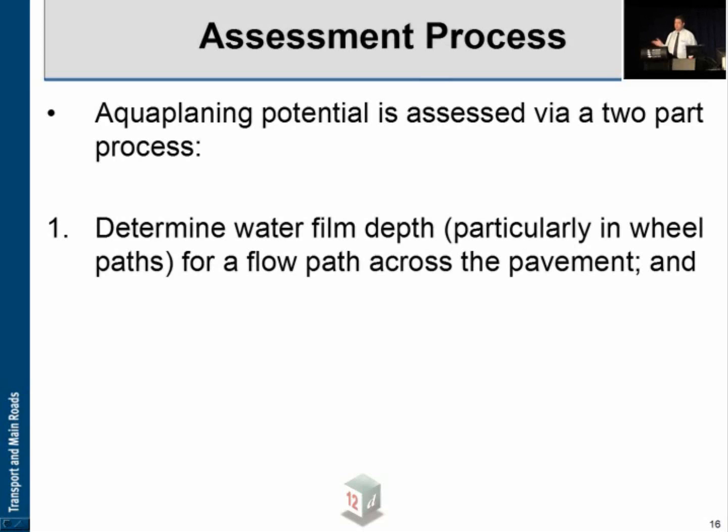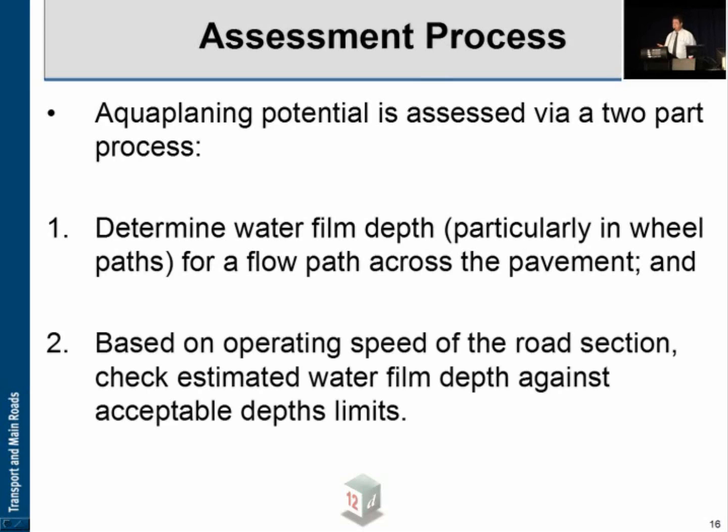The road surface is actually quite a wide area, but you've got a fairly good idea where the wheel paths, or the majority of the wheel paths, will go. So they're the areas we're trying to target. And we're looking at the whole pavement. It's really important when you get into ramps, interchanges, intersections, even roundabouts, etc., because you've got wider expanses of pavement that can capture water and direct it. And wide flat pavements like the motorways, etc.